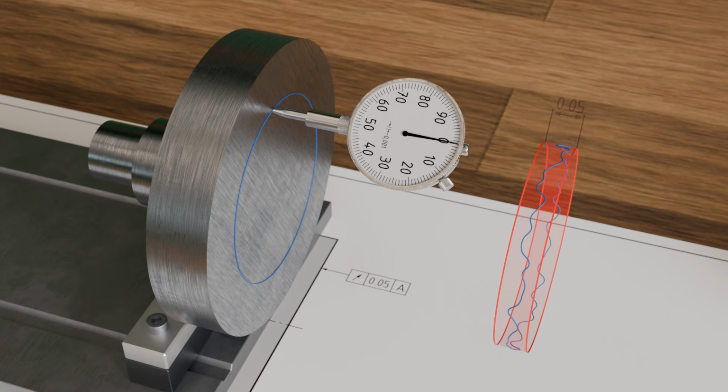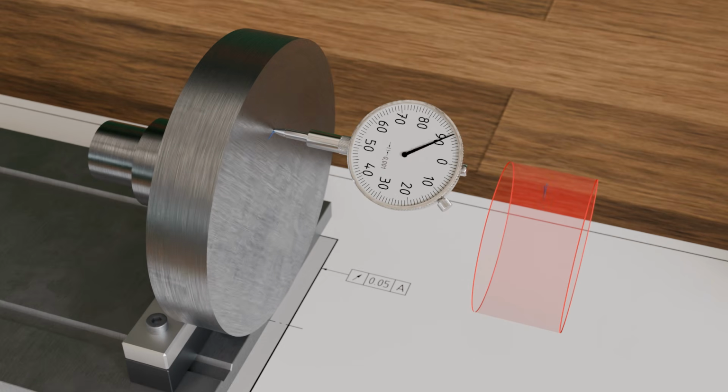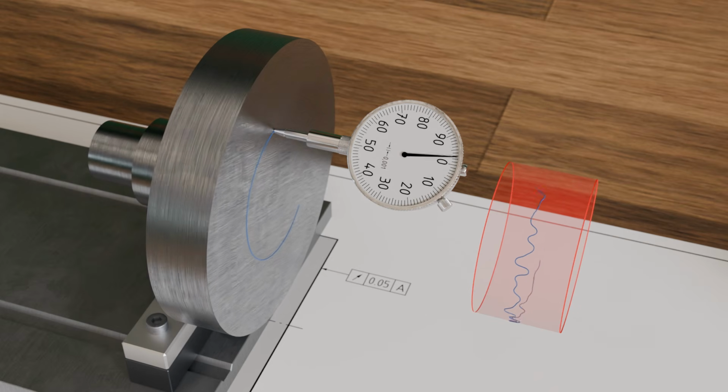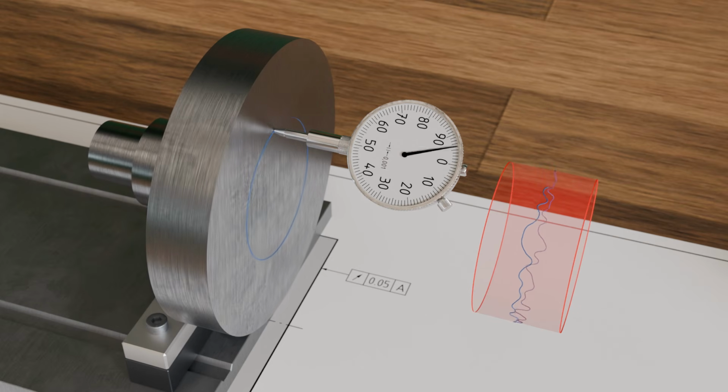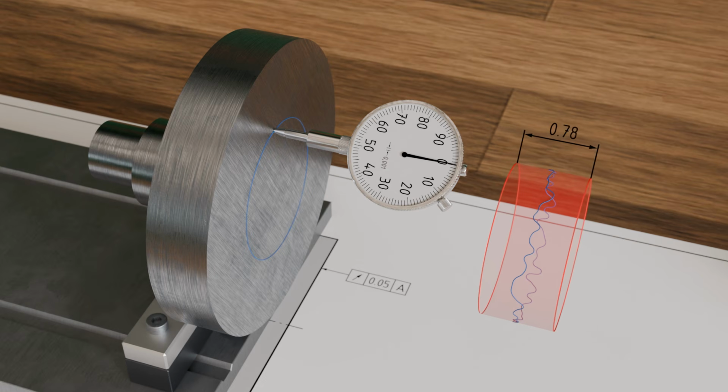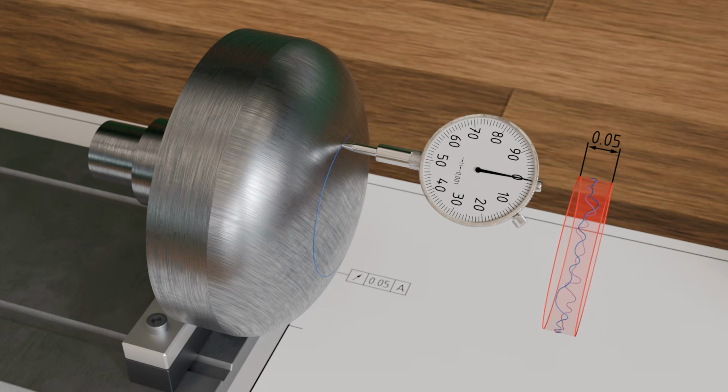To do this, the dial gauge is placed at a new location on the tolerated surface and the inspection process is repeated. Regardless of the axial position of the tolerance circles from before, the measured deviations must again lie within two circles spaced 0.05 millimeters apart. The tolerance circles are realigned in this way for each measurement. This procedure must be repeated at different locations on the tolerated surface in order to gradually cover the entire surface as comprehensively as possible. Since the tolerance zone is essentially redefined with each measurement, axial runout is particularly suitable for non-flat surfaces, such as a convex shape.